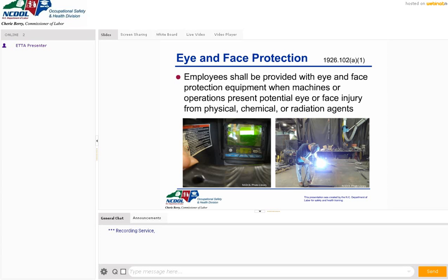Okay, a good safe welder is going to wear welding glasses or a face shield, okay, and they're going to have proper PPE. And you can see this guy, he's got gloves with gauntlets, but he's wearing a short sleeve shirt, so he's exposing himself to UV radiation, which essentially will cause a sunburn. But when it happens over and over again, the more your skin is exposed and the more burned it gets, the more susceptible it is to things like cancer.